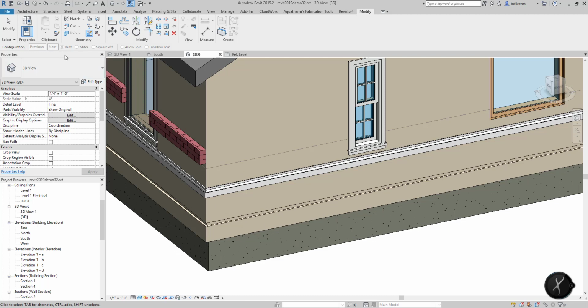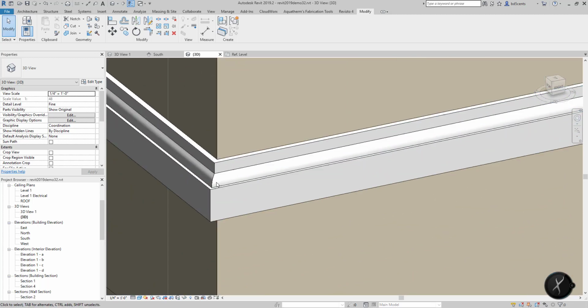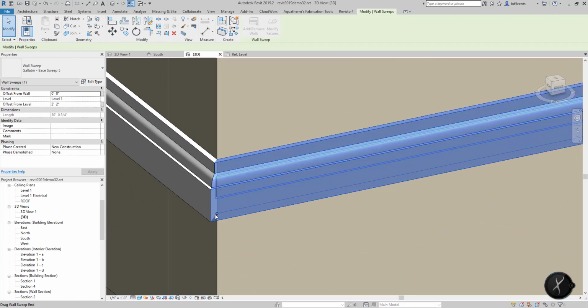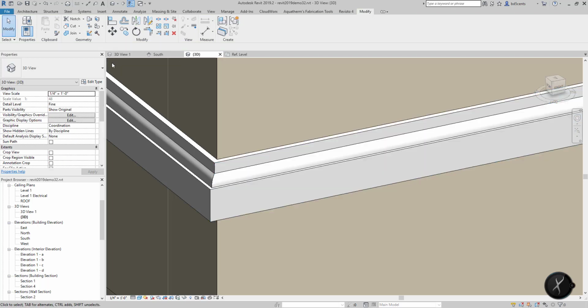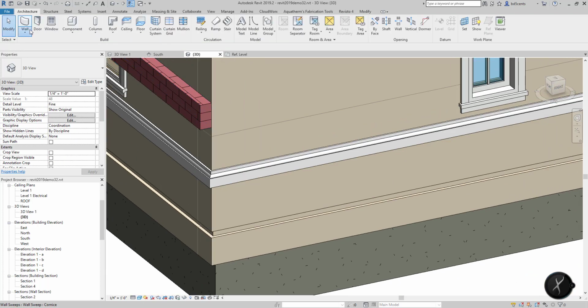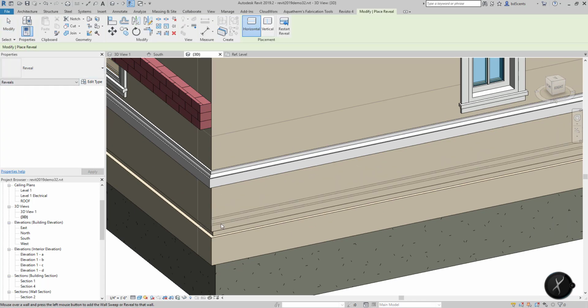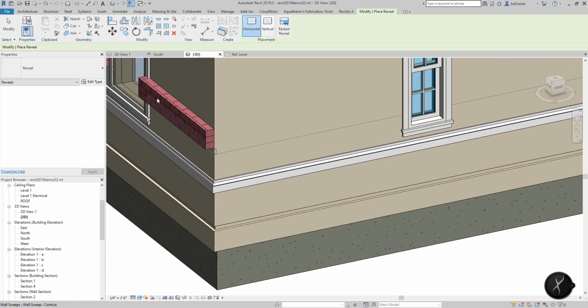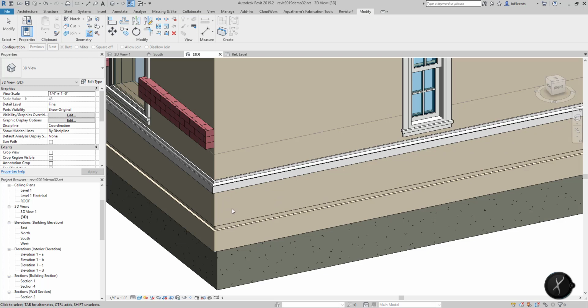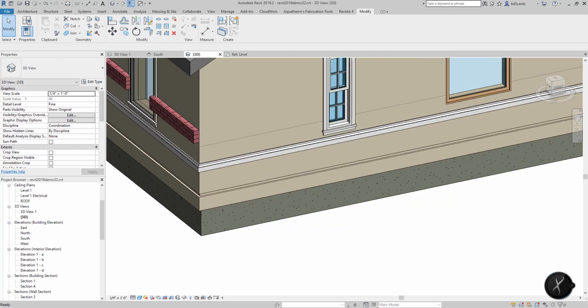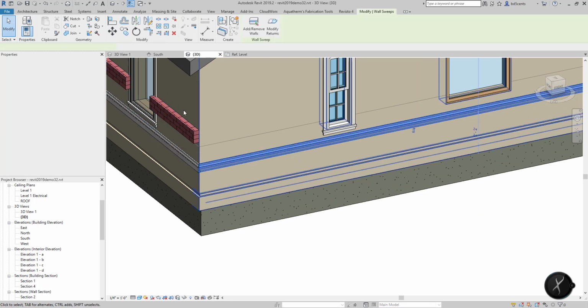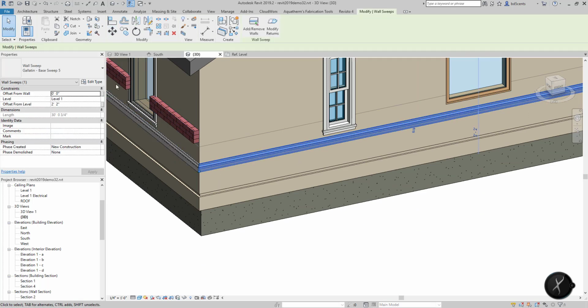We're doing a butt end. It's actually mitered here, and that would adjust what's happening to this end condition. That's just important to understand. If I create an architecture wall reveal as well, so I'm placing them in here, I can set this in condition, but it's not modifying it. But just know that under these conditions, you can edit the wall join.